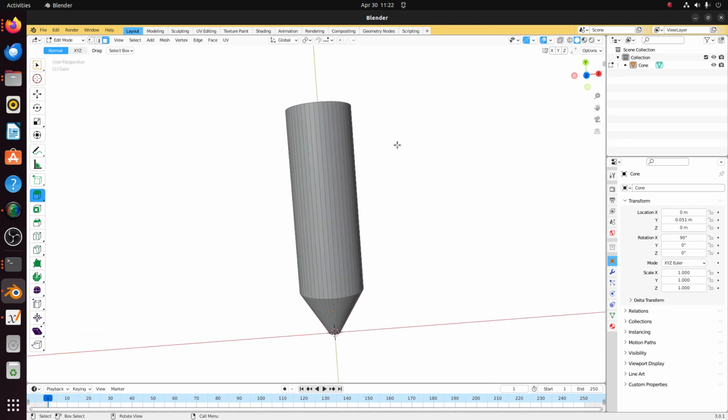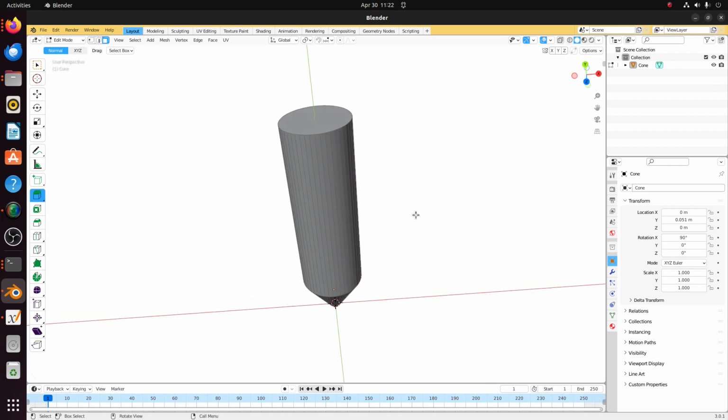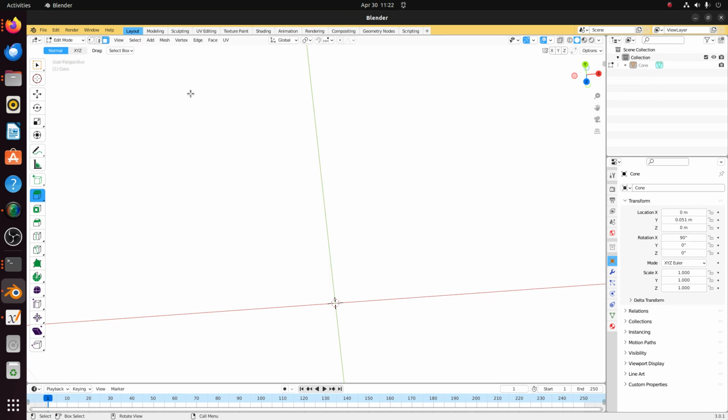So this is my outer geometry. So next I want to include a sparger in the middle, through which inlet of a fluid will be taking place. So we can hide this temporarily, and then the geometry for that is actually a torus shape.